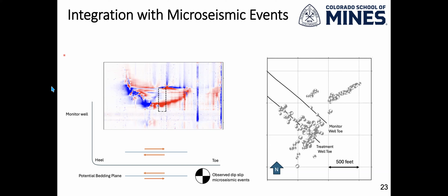Yes. I think the question is, you were discussing clay content and low friction coefficient at certain bedding planes based on that gamma ray log. And if it's pure shear, that would be right. I see what you're saying now. How can you have such a long-range pure mode 2 fracture? We observe in some other places, as well as in your case, very long-range communication, which would be very easy in mixed mode because mode 1 would propagate very quickly and far away. But in that case, it doesn't matter what the friction coefficient is, because we already opened the interface.